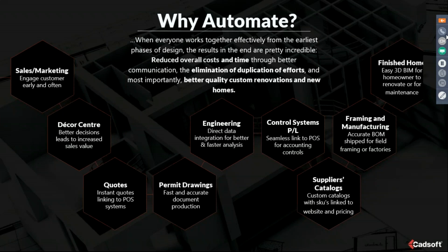How do you address multi-stud pack walls? For example, a double or a triple 2x6. So I'm thinking like a marriage wall when you're dealing with multifamily, if that's what you're speaking of. When we're designing those walls, we would just do a double wall in that area and handle those through there. But if it's just a framing configuration that you're showing them.